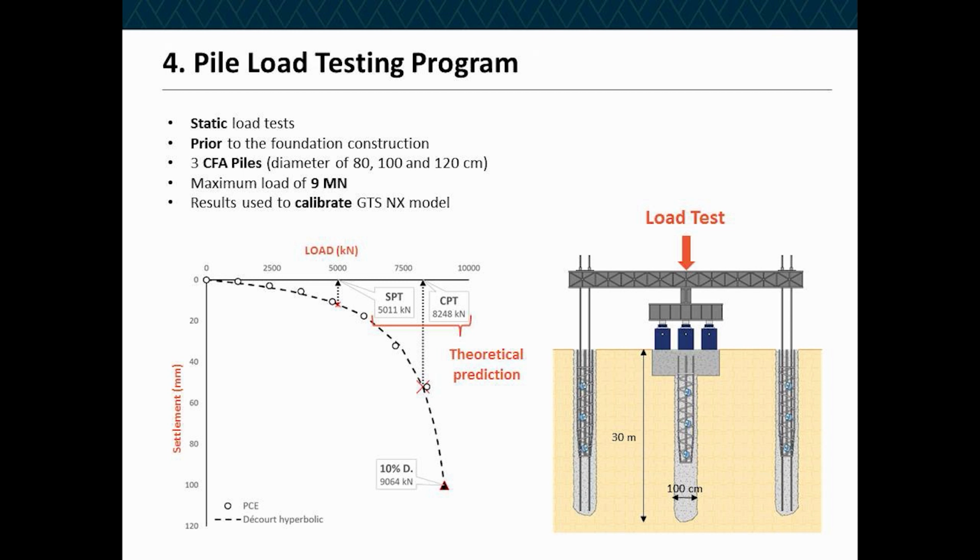settlement curve. So there's a difference between them, and the prediction of the behavior of the pile based on the cone penetration test method shows values much closer to those measured by the load test. This result is mostly explained because of the nature of the test, which is, let's say, much more technological than the standard penetration test.